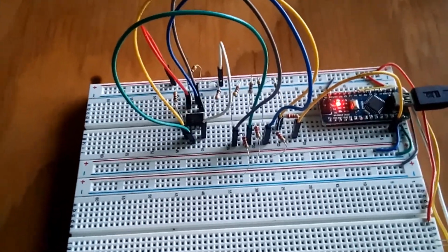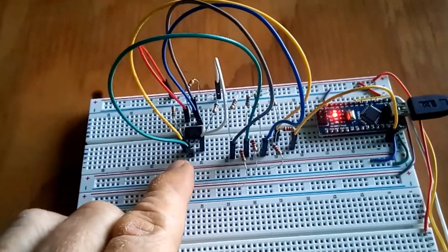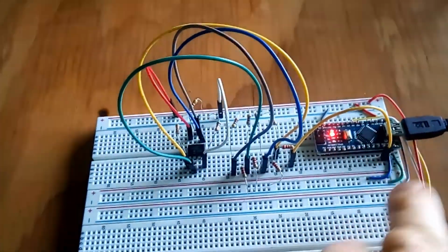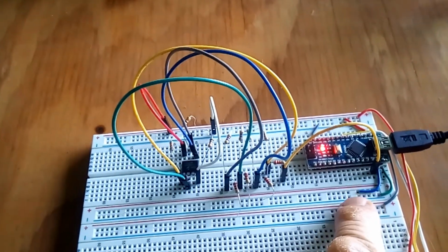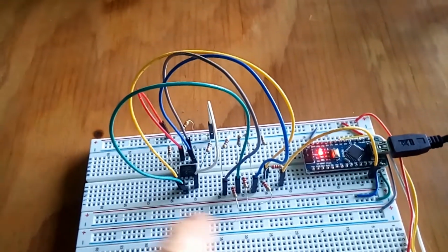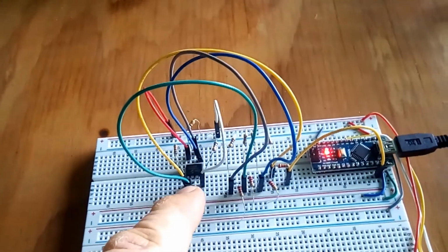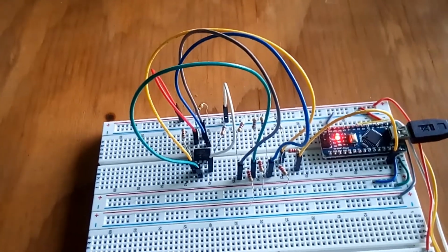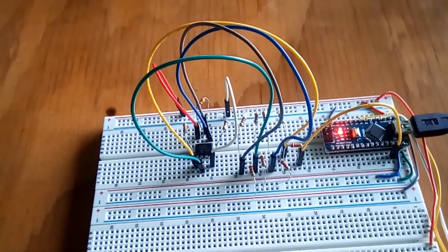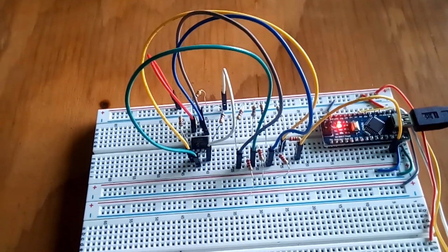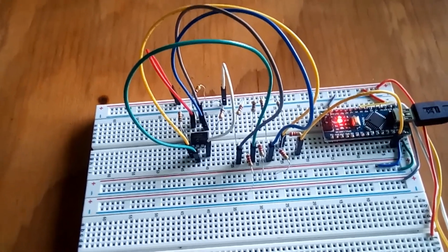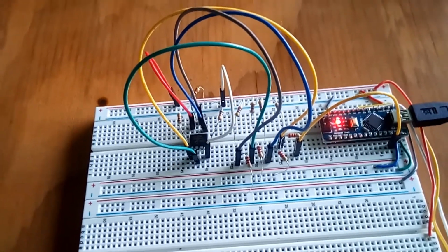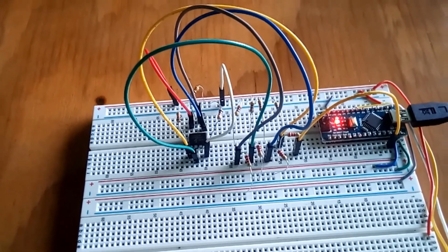Okay, so here's that chip in action. Obviously RAM's happening in the background, so there's not a lot to see here, but here's what it looks like hooked up. I usually hook up SPI communication to these buses. So I just have the SPI communication controlling the RAM, all the power, a bunch of voltage dividers to get everything from 5 volts to 3.3 volts. And again, RAM usually happens in the background, so I had to move it to the foreground in order to see something. Let's go look at the code running and see something from this RAM.